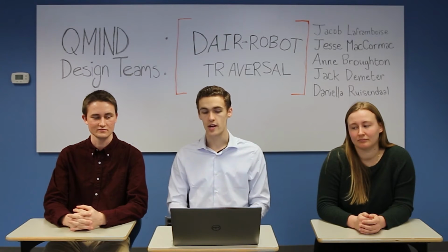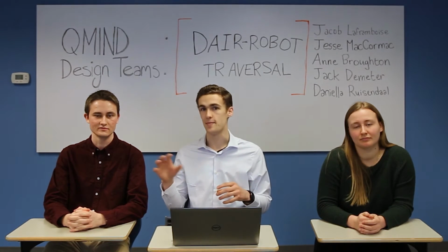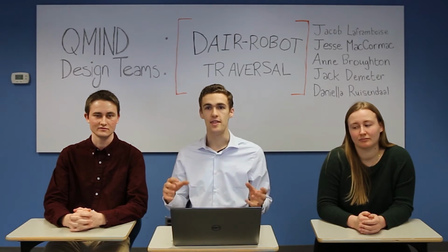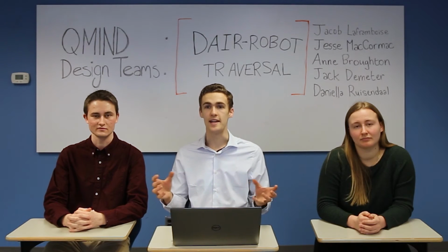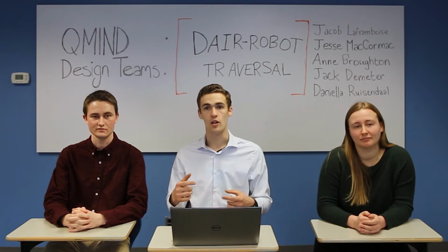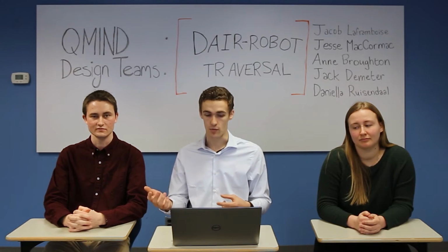In second semester, we pivoted a little bit, and so we wanted to utilize the camera on our robot to identify, localize, and then avoid potholes. So we're working on the robot operating system, which allows us to create a set of ROS packages or nodes. And these nodes work asynchronously, they can all run in parallel, and they can communicate between each other, along with a number of built-in nodes that come with ROS.